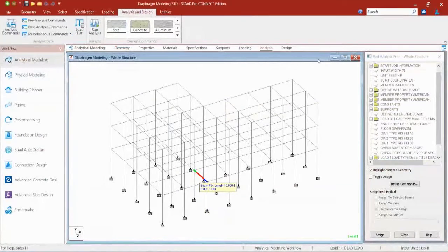So what am I going to do with this information? Well, I'm going to look in my building code, which for me is the ASCE 7. I'm going to check which types of irregularities I have. Depending upon the information that I see, I may have to consider which type of analytical procedure I can follow. I may not be able to do just a static seismic load according to the equivalent lateral force procedure. I may be required, depending upon this information, to do more of a dynamic seismic analysis.